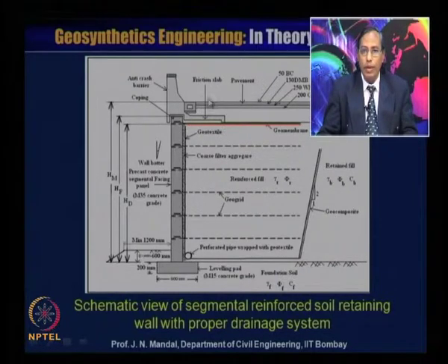So, you are providing some design of the pavement here, where you have 200 GSB, 150 WMM, 130 DBM or 50 BC, or you can provide geotextile material to reduce the thickness of the pavement.